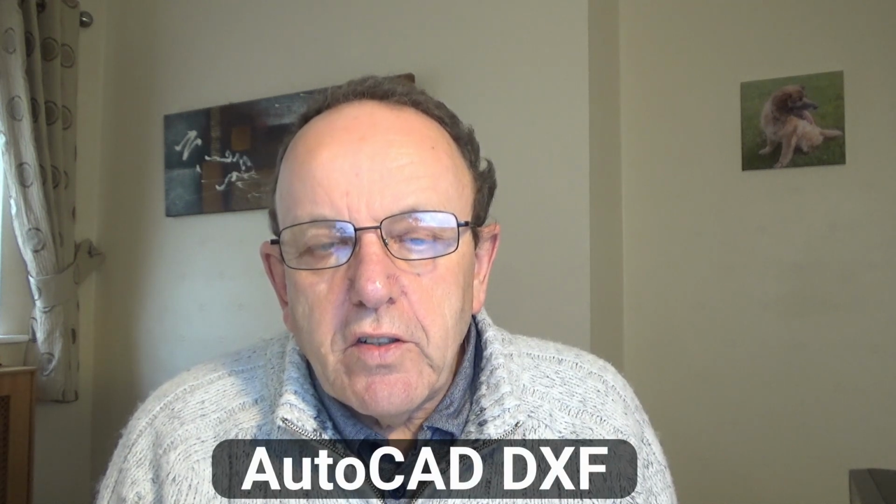What we'll do is have a look at each one, and if you are thinking about building a foam cutter, one of the things I suggest you do is have a look at the software first, because I've had a few guys contact me. They've built fantastic machines, and then when they come to generate the G-code, they get a little bit disappointed. It's usually because they've got a CAD file, like a DXF file, and they're trying to load it in some software, and there's only a few that will load them in, and sometimes it will and sometimes it won't, and then they get a little bit disappointed. So do check on the software first before you think you're going to build a machine.